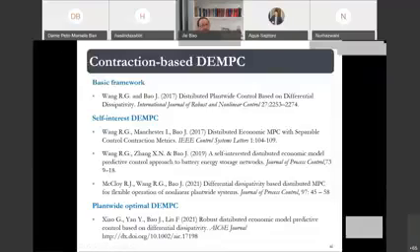When we do that, we cannot get away from iterative optimization, because we try to minimize the plant-wide cost, so you have to negotiate with each other. But the idea is that we minimize the iterative optimization as much as possible, and we use the dissipativity supply rates as a vehicle to do the negotiation.